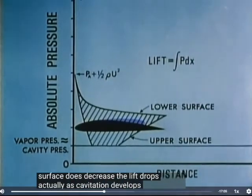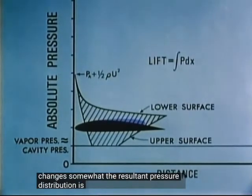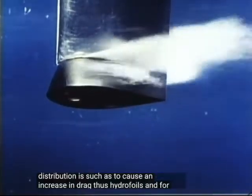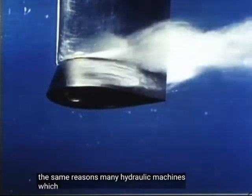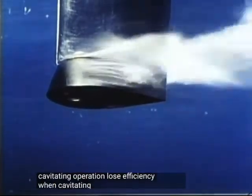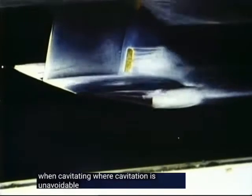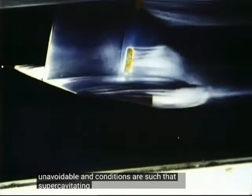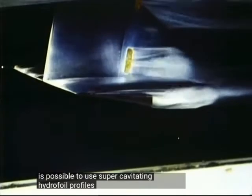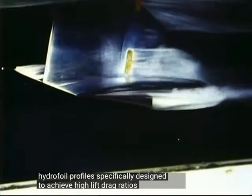Actually, as cavitation develops, the shape of the pressure distribution changes somewhat. The resultant pressure distribution is such as to cause an increase in drag. Thus, hydrofoils, and for the same reasons, many hydraulic machines which are designed for efficient subcavitating operation lose efficiency when cavitating. Where cavitation is unavoidable and conditions are such that supercavitating flow can be assured, it is possible to use supercavitating hydrofoil profiles specifically designed to achieve high lift-drag ratios.